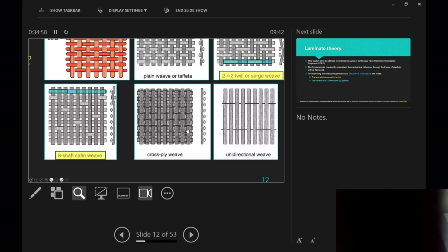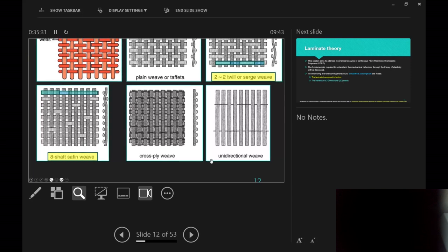What's happening here? Exactly. Very strong, and they've got some threads holding it together. If you look at it, it's essentially a mesh of thread, or whatever you want to call it, putting everything together until it goes into the autoclave and it's cured and everything sticks together. Essentially, these are there just to hold things together. And the king of all is unidirectional weave.